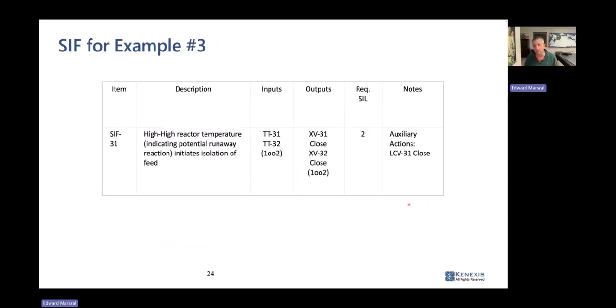If you do include it in your safety function, you'll have XV, LV in a 1 out of 2 vote, in an OR gate with your level control valve in a 1 out of 1 vote. There's no way that that set of equipment is going to achieve SIL 2.